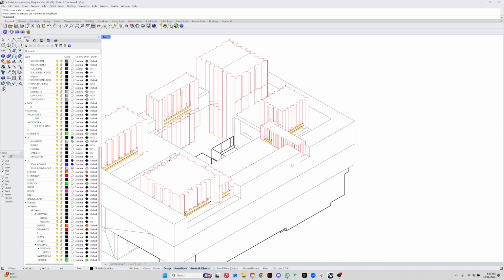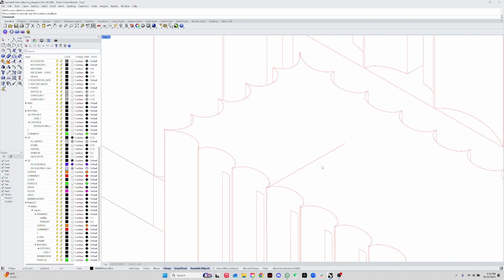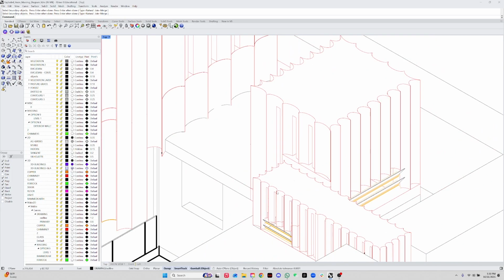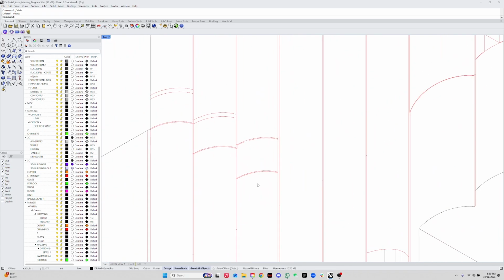Now, when you have this, obviously there's going to be a little bit of imperfections depending on your model, how you modeled this. Like you see how I'm getting these weird lines or some things are not connecting. The Make2D is never going to be 100% perfect. So what I would do now is go in and start fixing the model as much as you can, so then the diagram is clean. Depending on how much resolution the model has, I'll go in and start cleaning. And at least with the script, it does it the best possible, so you're going to have minimal work.